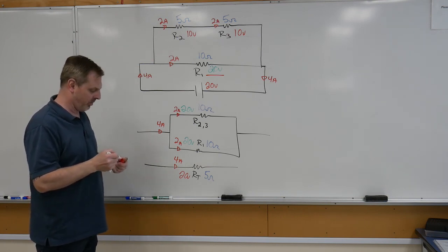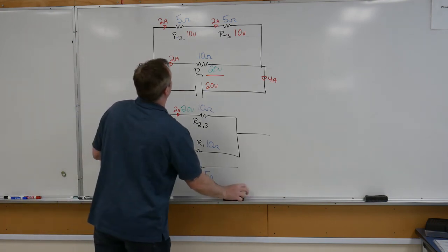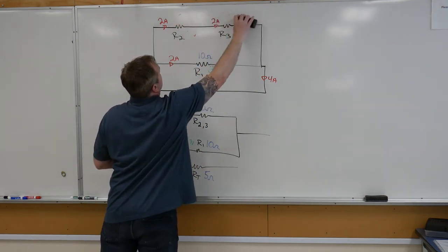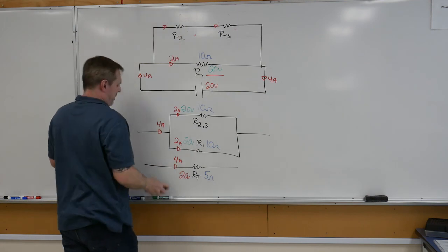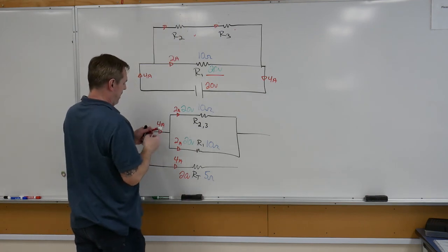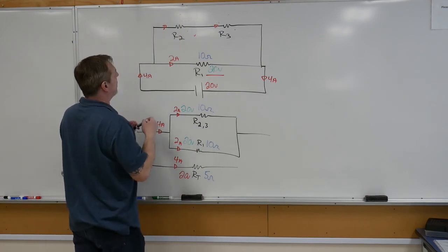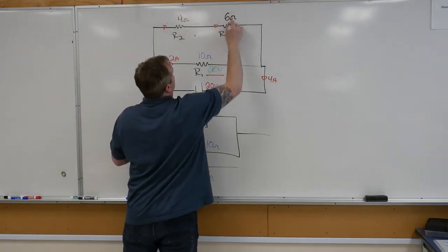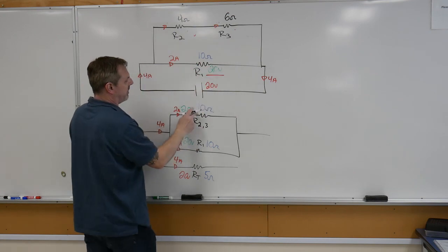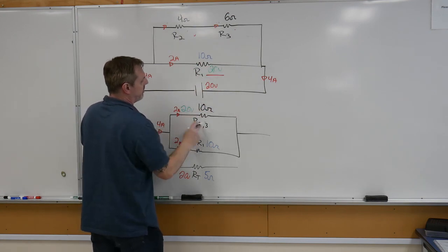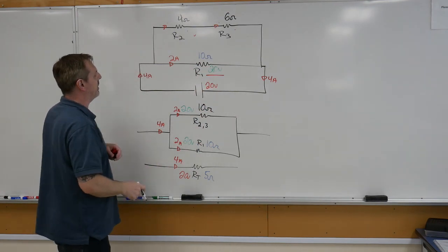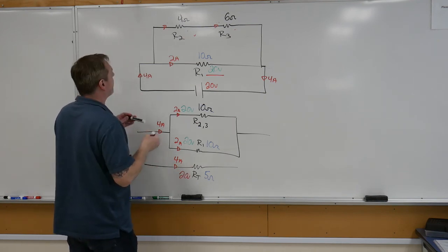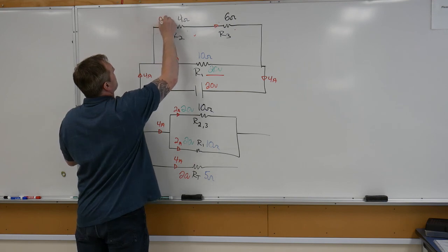So we've got lots going on. If I were to change this value around a little bit up here, but still keep the resistance total to what would have been 10 ohms, okay? Let's say that this value up here at R2 is 4 ohms, and this value here is 6 ohms. 4 plus the 6 would have still equaled the 10. Okay, so nothing's changed in the way that we calculated it. Okay, the R total would still be the same. The current flowing in this upper branch would still be the same.